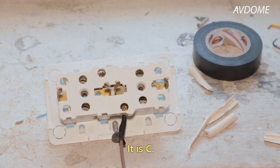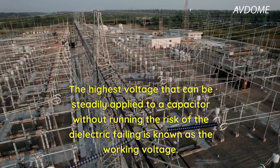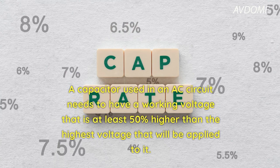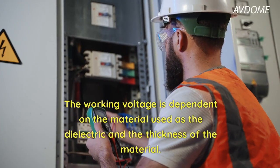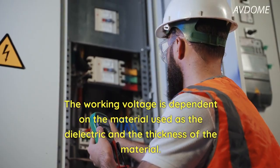It is C. The highest voltage that can be steadily applied to a capacitor without risk of the dielectric failing is known as the working voltage. A capacitor used in an AC circuit needs to have a working voltage that is at least 50% higher than the highest voltage that will be applied to it. The working voltage is dependent on the material used as the dielectric and the thickness of the material.